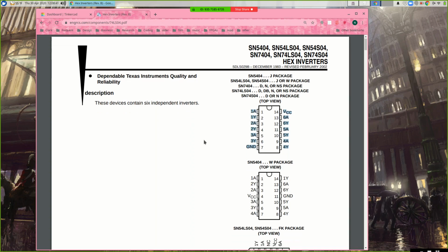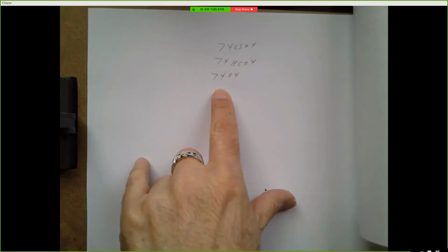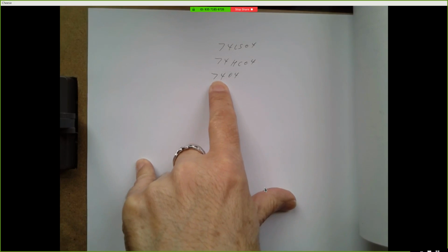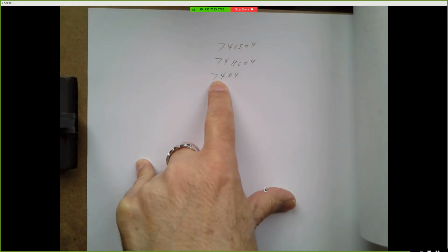Okay. There's another set of chips called 54. There's a 5404, a 5408, and so on. Different chip. Okay, remember this number in the beginning is what type of chip it is. 74 is the standard commercial grade digital devices. 54 is what are called mil-spec devices.